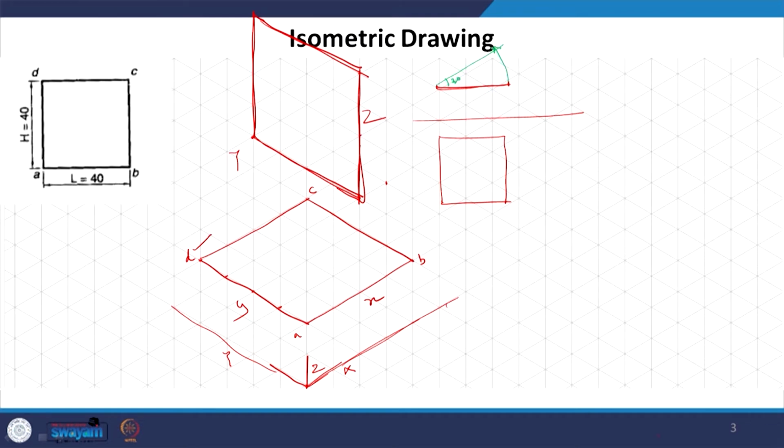So, we will draw this at 30 degrees. You take this projection, and this is the plane as seen in front elevation, we bring it back. So, the new thing which will be seen is this. Now, if I am drawing this here, what will happen? So, we draw the original plane first. If the original plane was here, this was, say, the same dimensions. So, this was parallel to xy. Now, we say that it is making an angle with the horizontal plane. Now, how do we get that angle?